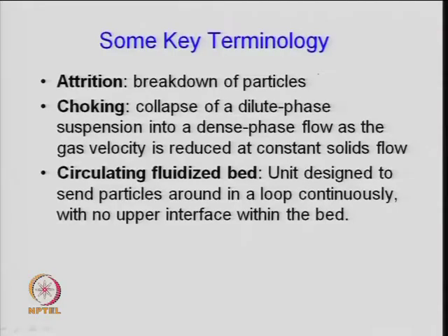In that, the terminology which is generally used, as I said, is attrition. In fluidization the particles are moving up, and there are forces acting between the particles. So, particles should have good attrition resistance. If the material is soft, then it will crumble, and because of that the particle will become smaller in size and will leave the bed, or you will have a loss of the catalyst material. So, that is again important. Attrition generally refers to the breakdown of particles.